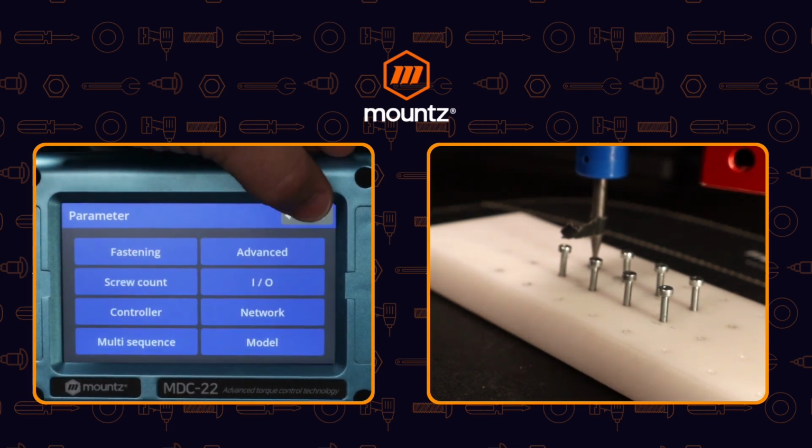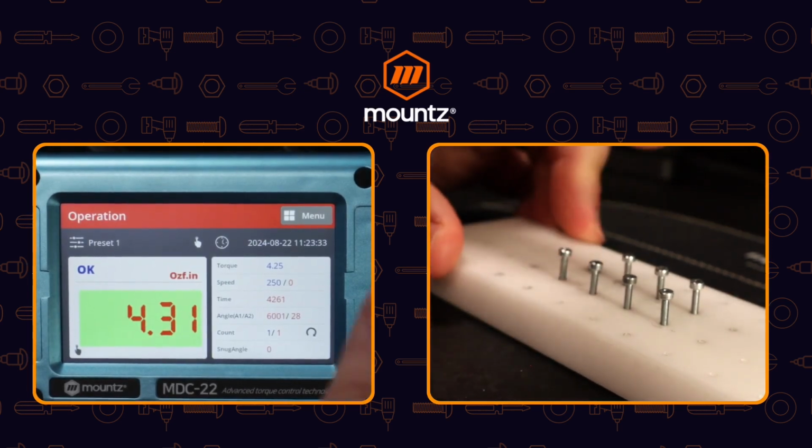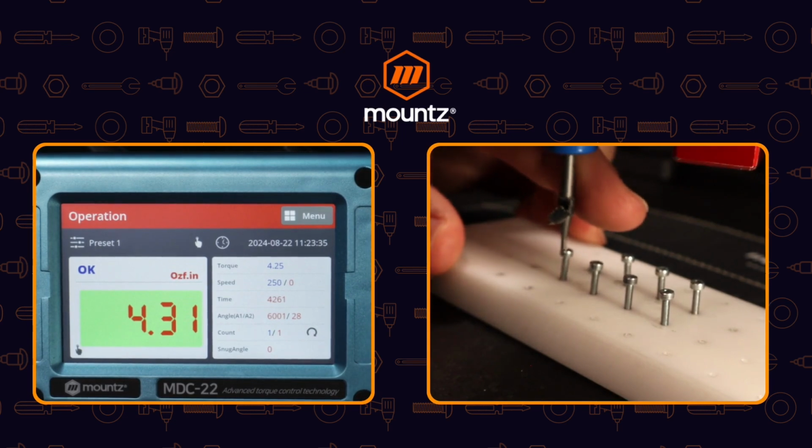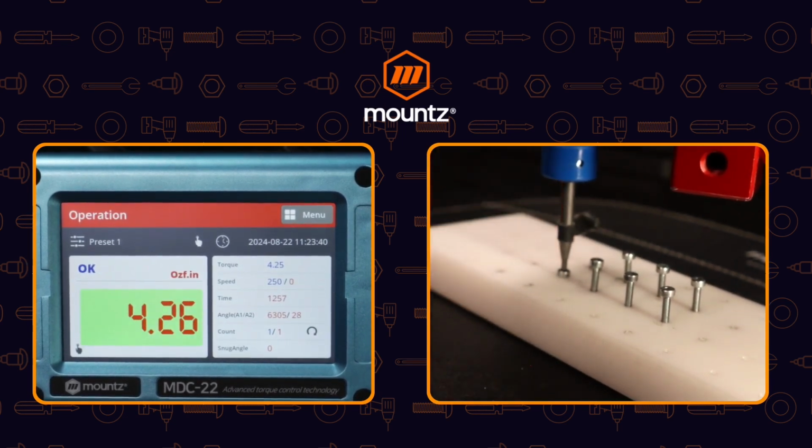So if we come back out to our preset, and now we go ahead and run this down, you can see that that was a much better and faster rundown, and we still were able to be at our 250 RPM right as the fastener is being seated.